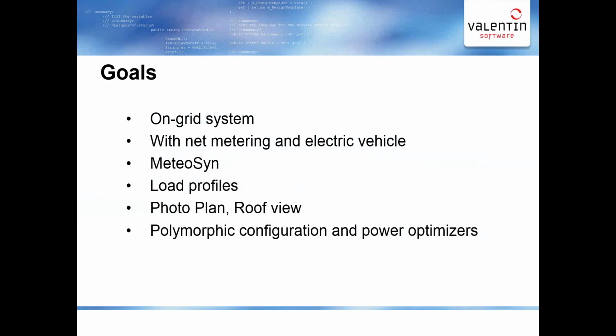Last but not least, we will also show you the polymorphic configuration and the working with power optimizers. Polymorphic configuration means if you have, for example, two roofs with different orientations and you want to configure them to the same MPP tracker of one inverter.